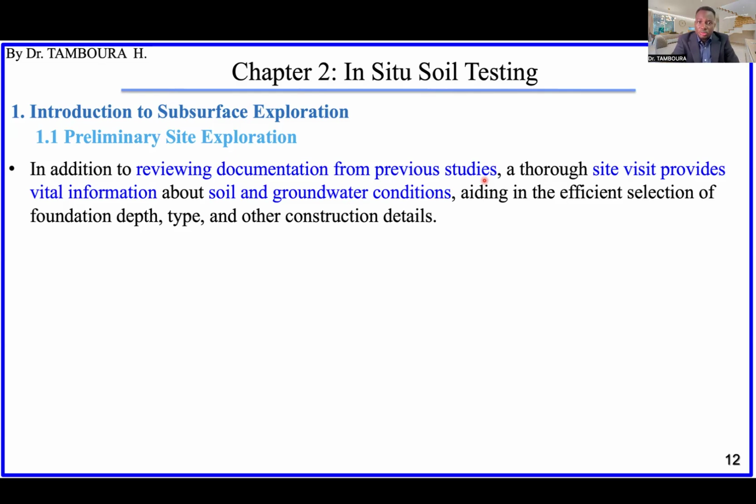Maybe you will notice something that is not included in the documentation you have gathered. You may see that there is a new construction going on near the site where you want to build your structure, or a little change of vegetation, something like that. By going, you can have more detail, some detail that a photograph could not show you.